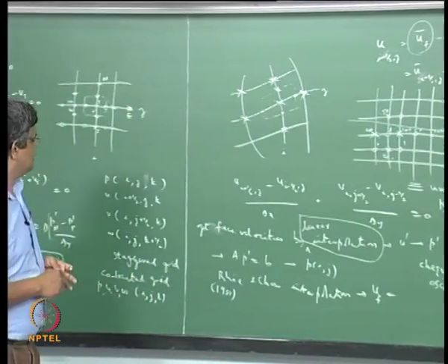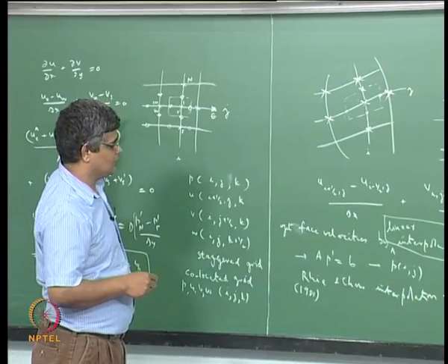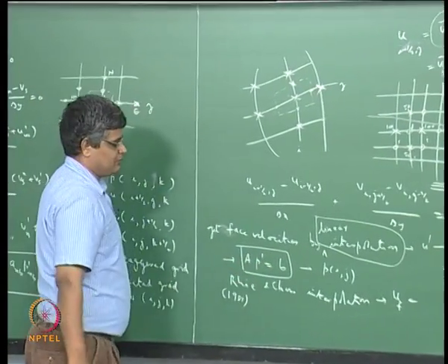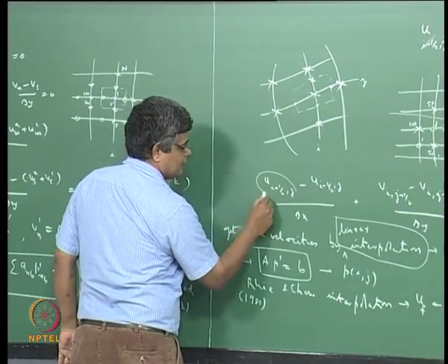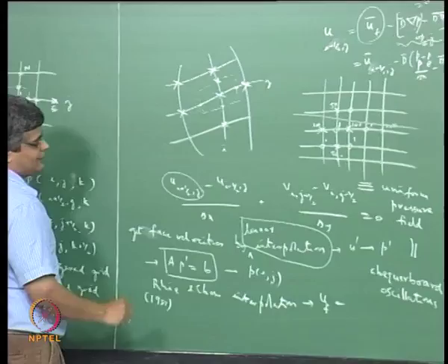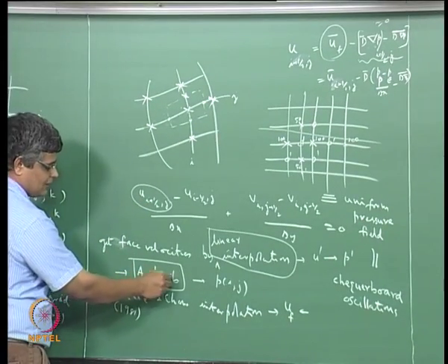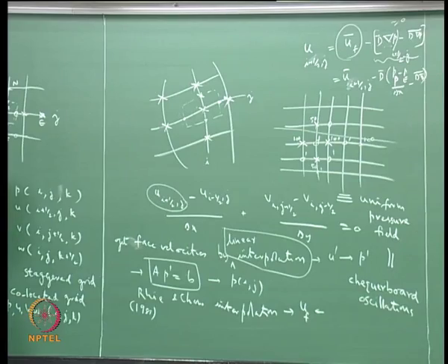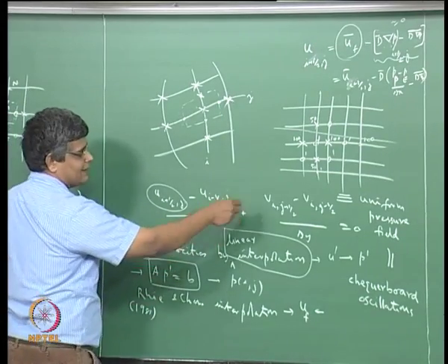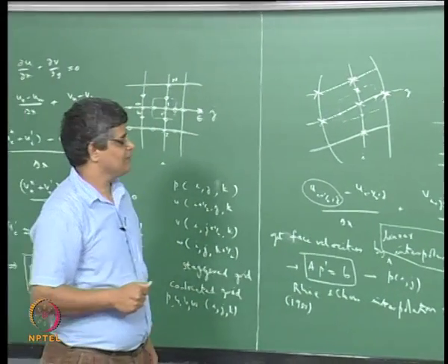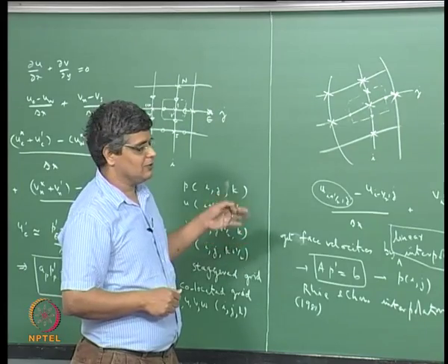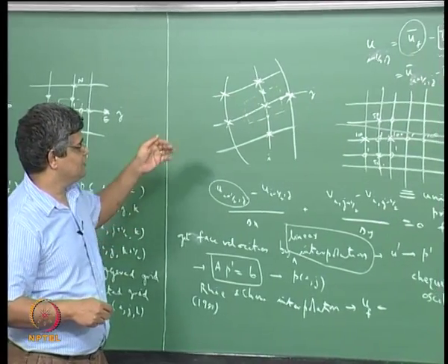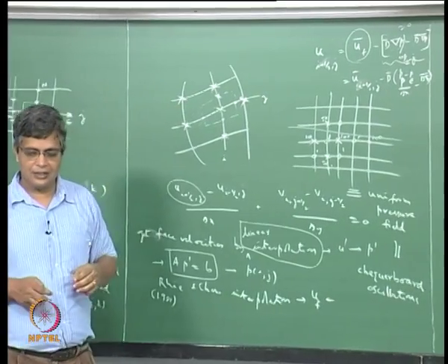With this approach, when we add this to the overall determination of pressure in the context of determining AP prime equal to B type of solution with interpolated plus pressure corrected phase velocities, then it will lead us to an equation for AP prime equal to B, which can be solved along with the discretized momentum equations to give us the pressure and velocities at the same point, they are collocated, and with this type of approach one can in a fairly straightforward way use a body fitted grid for the calculation of the velocities.